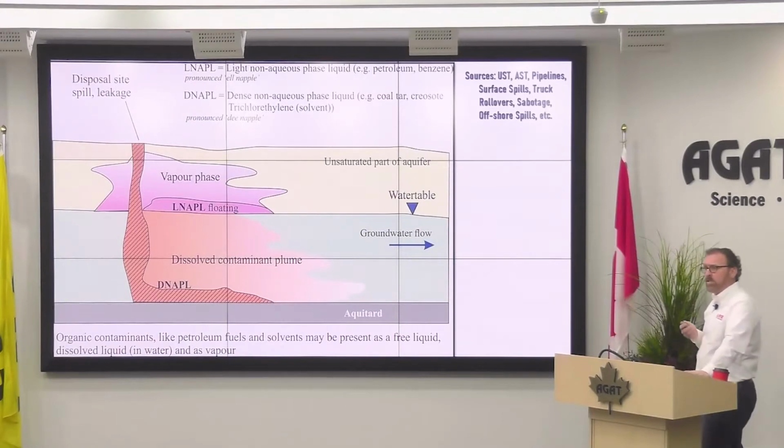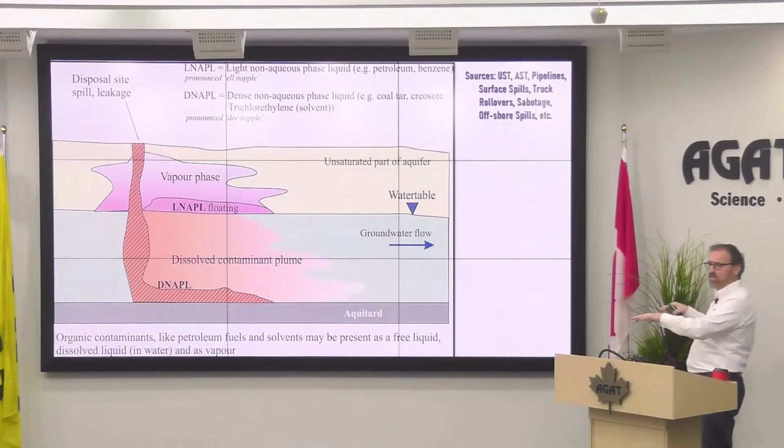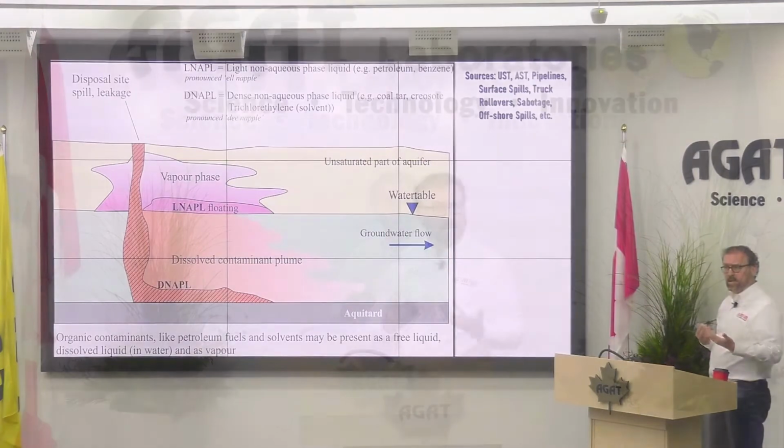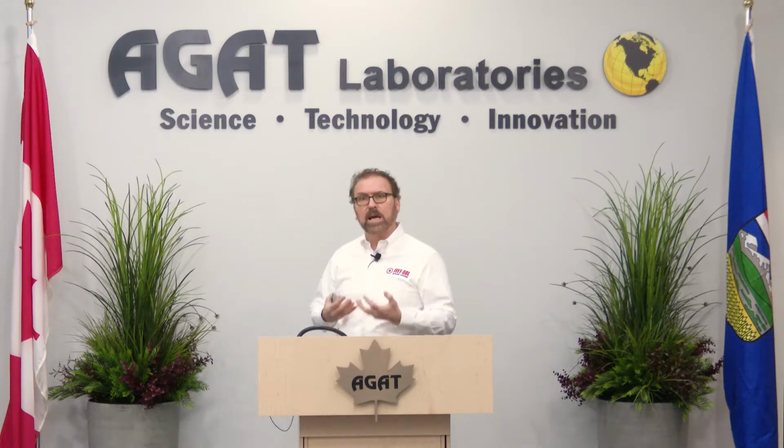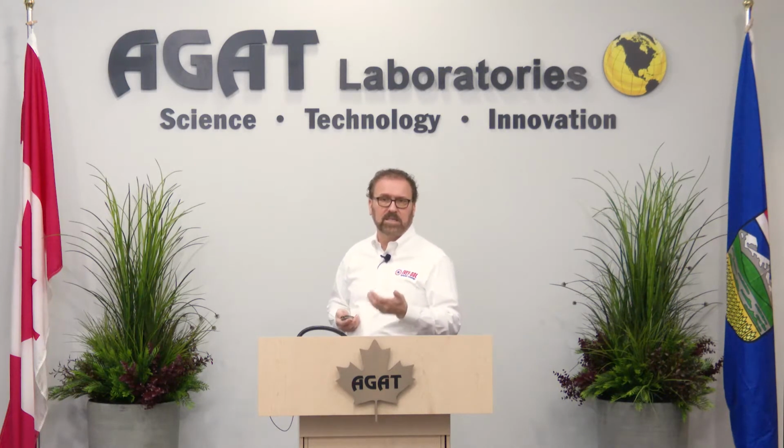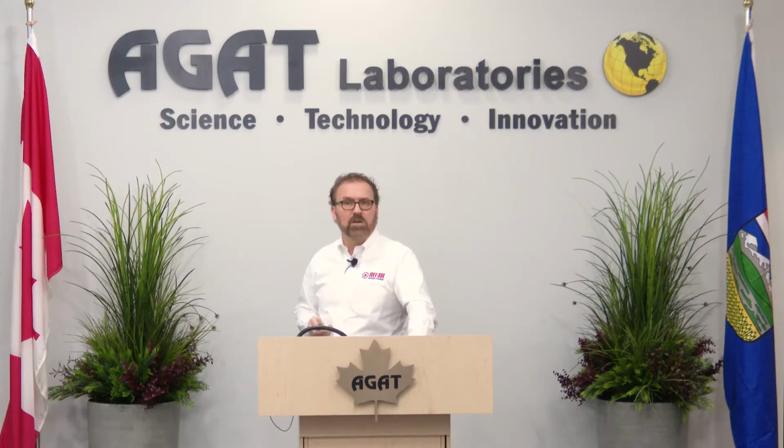If they're light compounds, they'll come in contact with the water table, and the movement and depth of that water table will probably slow it down, and it'll tend to follow that pathway. If they're a little more dense or intermediate density, they'll keep going down. If they're particularly dense, they'll keep going down until they hit some kind of confining layer. Could be bedrock, could be a really tight, stiff geology, and then it'll migrate from there, typically following the groundwater flow, okay? So this is not uncommon to us, but it happens at a lot of sites.